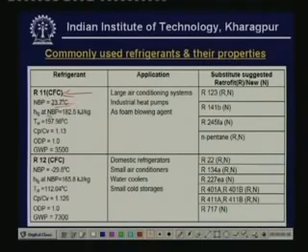And the specific volume of the refrigerant will be very high because the pressures are low. So, these are two disadvantages of this particular refrigerant. However, since it has other advantages, this is still used and it is mainly used along with centrifugal compressors, because of its high specific volume. Its latent heat of vaporization at normal boiling point is 182.5 kilojoule per kg. Its critical temperature is almost 198 degrees centigrade, which is good, and its isentropic index of compression is 1.13. And its ODP is 1 and its GWP is 3500.